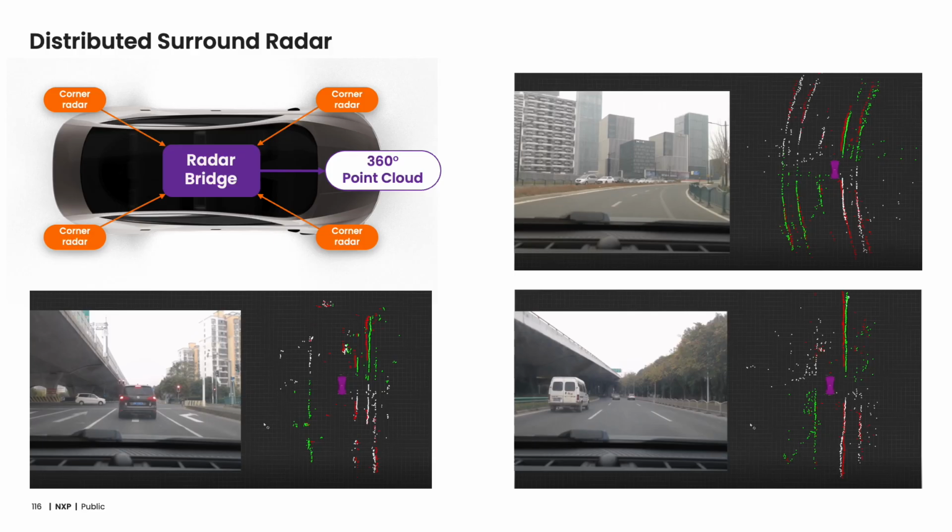This actually just uses 4 corner radars, which are providing the 1D FFT, and then a standard signal processing flow that you've seen in the previous slide that results in a point cloud, and we use it for a 360-degree radar surround detection. And we took it on the roads and performed remarkably well. I'll point out that you can see quite clearly road boundaries. You can see other vehicles are represented there. And this is the data in its most unrefined form.